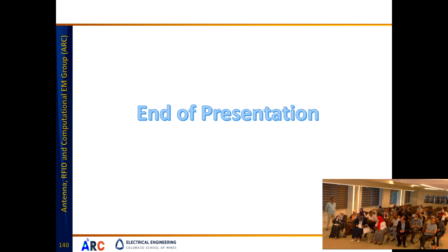You can't read it immediately. You can't change the location of the sensor from two different temperature regions immediately and expect the temperature to be recorded accurately. It needs time.